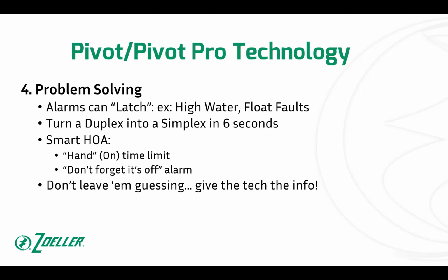I've got a duplex panel or system. I've got a pump down. It's going to take me a few days to get apart. I have to rewire all the switches on a traditional panel so that I don't create alarms every time that panel wanted to run the pump that's down. Now it's just a matter of pushing a button on a duplex. You just push it, you tell it, hey, this pump's out of commission. You're now a Simplex, and it won't give erroneous alarms for the pump that we already know is down.